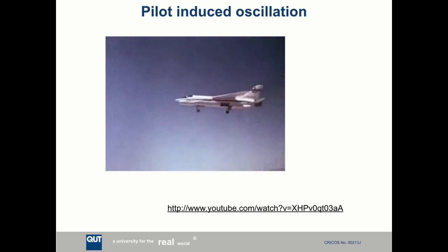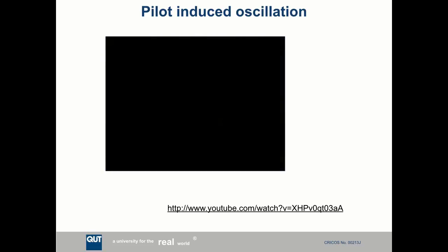So, if you go and consult YouTube about pilot-induced oscillation, you'll find a lot, particularly the shuttle. There are lots of shuttle landings where there's evidence of pilot-induced oscillation. Scarier there because he doesn't have engines, so he's got quite limited control authority. So again, an example where the delay in the control system, which is mostly cognitive delay in the human pilot, between what's being sensed, there's a control algorithm going on in here, and then he's actuating the sticks, is causing the system to become unstable.